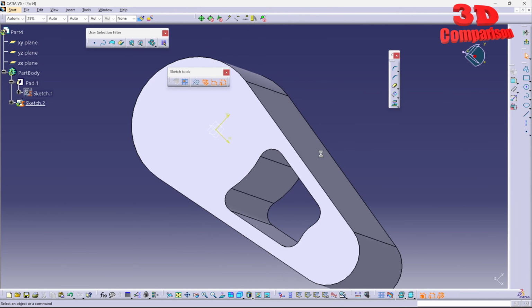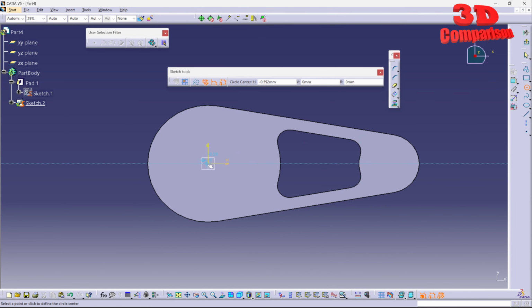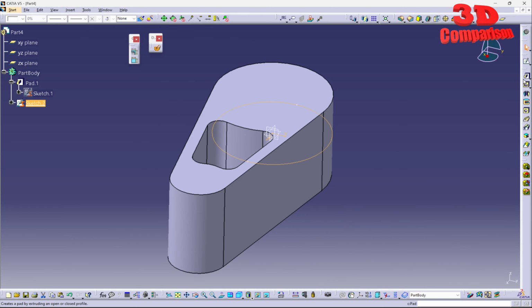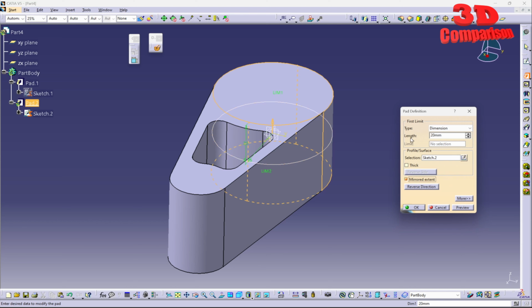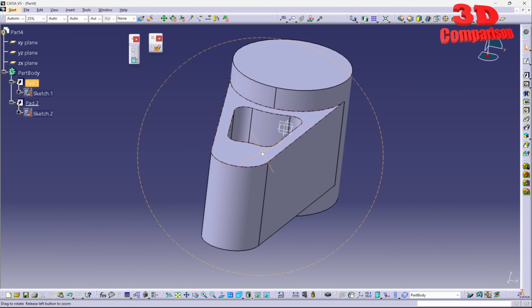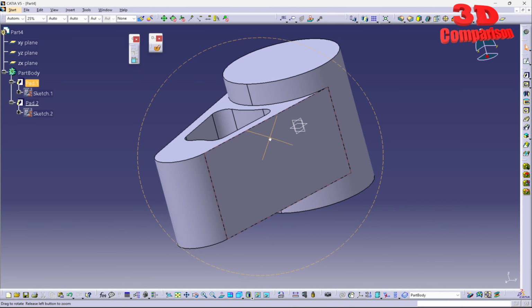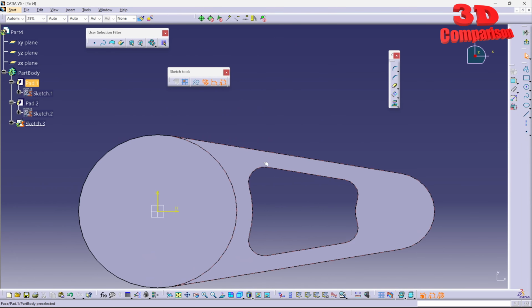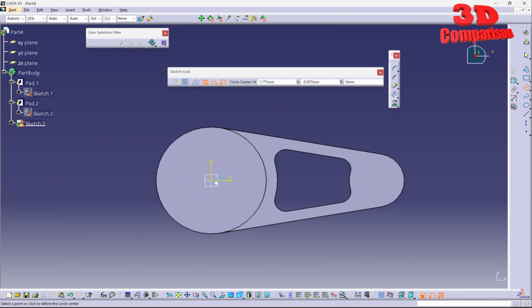And now I will create the cylinder over here in the middle. And this is the one which will cause problems. This will be radius 25. I want to have this padded. Length will be 30. And we have that edge appearing over here. And again, this is because of how we started the sketch. So it's quite difficult that we always need to compensate and make sure that those edges will not be in the important areas. In my opinion, that is not a good option.